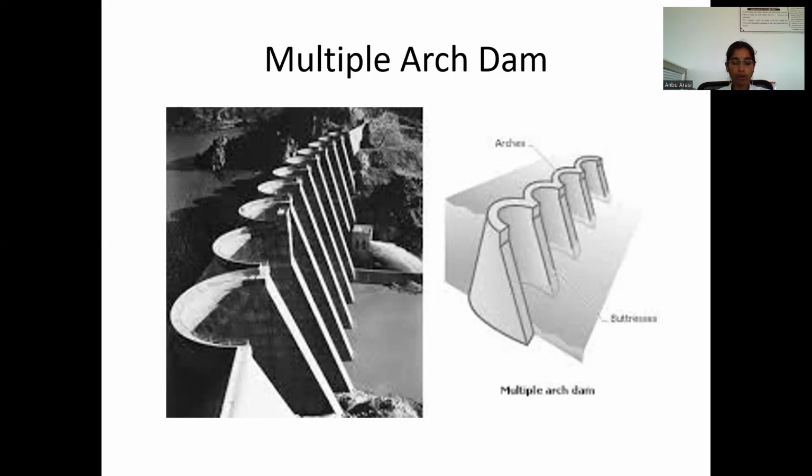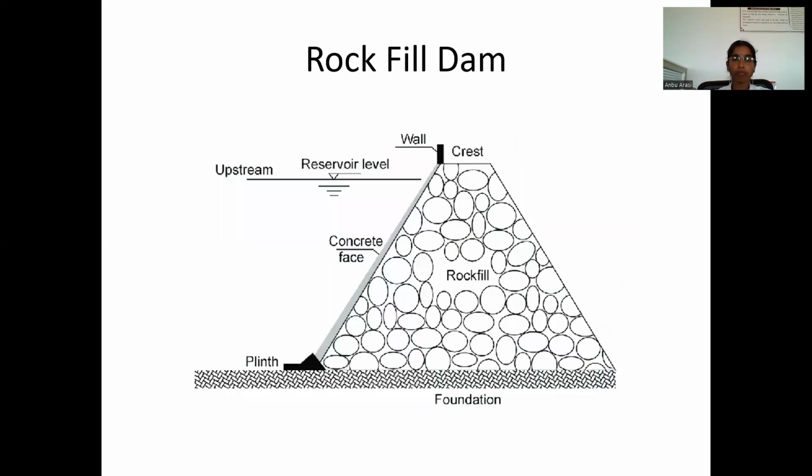Thin arch dams require valleys to have a crest to height ratio of under 3 with a radius of under 150 meters. The pressure exerted on the valley side is between 5.5 to 8 megapascal, where there is a vertical radius of curvature as well as horizontal. This is known as a dome type, used where cement is expensive and labor is cheap.